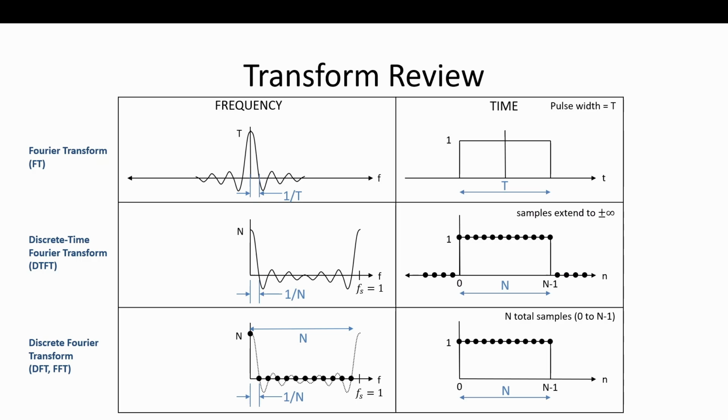The same thing, if you swap time and frequency, you'll see the same result. So if it has a width T, where it hits the null the first time is 1 over T, and then the other nulls are multiples of it. Okay, but that's going to help us see some stuff here. If you keep that in mind, the null's at 1 over T.